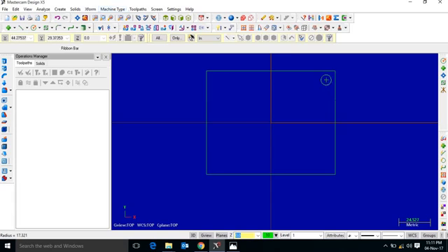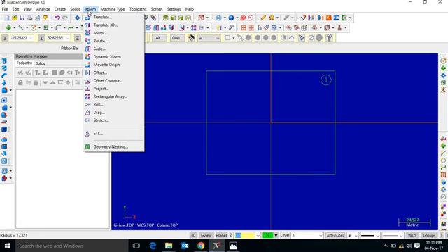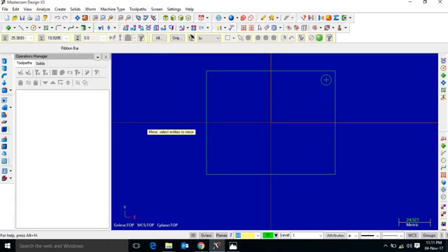now the same position of the circle, that is a symmetric circle, we have to draw. So here we can use a mirror command. Mirror command is in Xform. In Xform there is one mirror command. Mirror select. The software indicates what you have to do. The editor mirror, select the entity to mirror. Select the entity. That is, this was the entity.